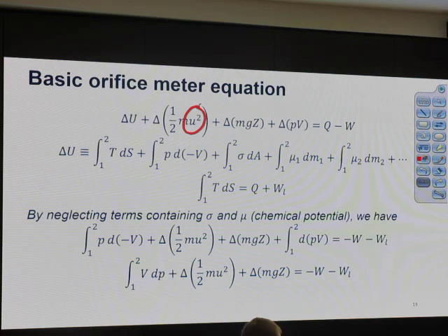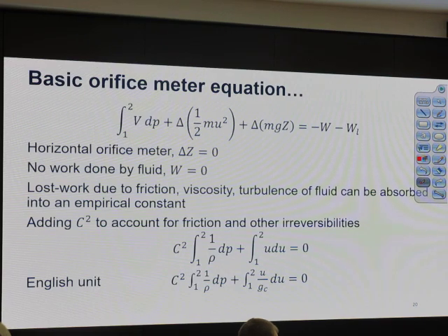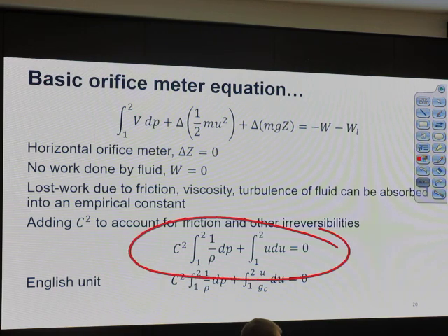Anywhere that we want to calculate the kinetic energy, you see that delta sign is before and after. We do the energy balance across the orifice plate. So your job is to know that u is the velocity of gas. Okay. m is mass of gas. z is elevation of gas. Okay. Alright, once we do the math, the macroscopic energy balance reduced to this, we have u du.